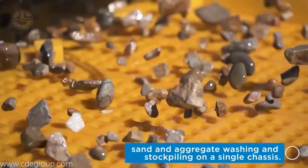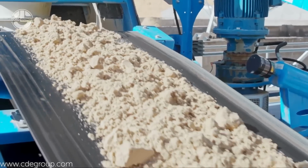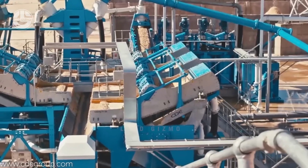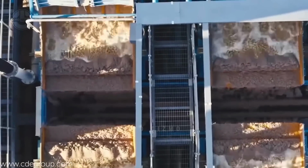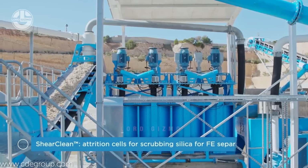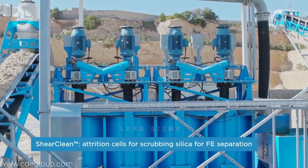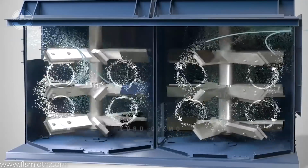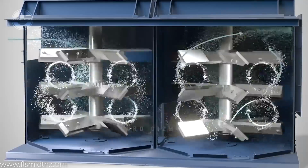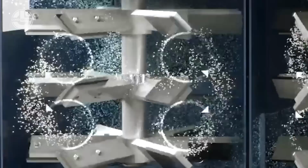Upon vibration, sand particles of a certain size can only pass through these openings. In this way, the coarse sand is separated out and stockpiled for coarse construction use. This refined silica sand now has to go through attrition cells. These cells clean the surface of particulates, removing unwanted contaminants, impurities, and pollutants. This process includes removing clay slime and cleaning surfaces of soft or conglomerate impurities.